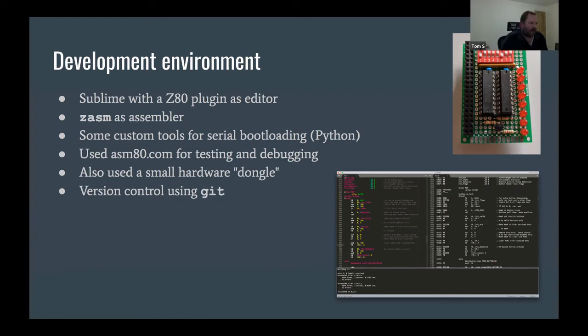But it also had a second hotkey like Control R, which I guess is for run, and I was really hoping to use that with the serial bootloader and maybe use something like the DTR signal to kind of reset the processor, which would then restart the bootloader, and then I could upload the code that had just been assembled and then start executing it. But I couldn't quite get that working with my FTDI cable.